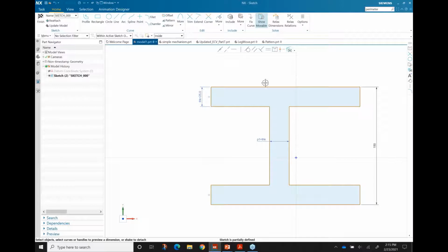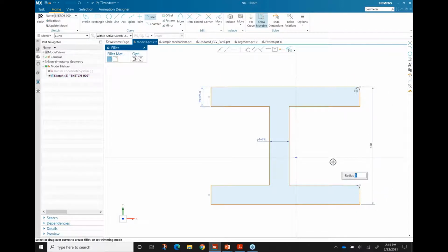There's a couple other cool things that we can do with the new sketch. Now, one of those is when you wanted to place a fillet. So I'm going to use a fillet, and I'll just go with a 5mm. In previous versions, you'd always have to click, click, and click, click to get it to work. 2 button clicks. But with the new version, I can just click and drag. And notice just how fast I'm able to put those fillets in all around my part.